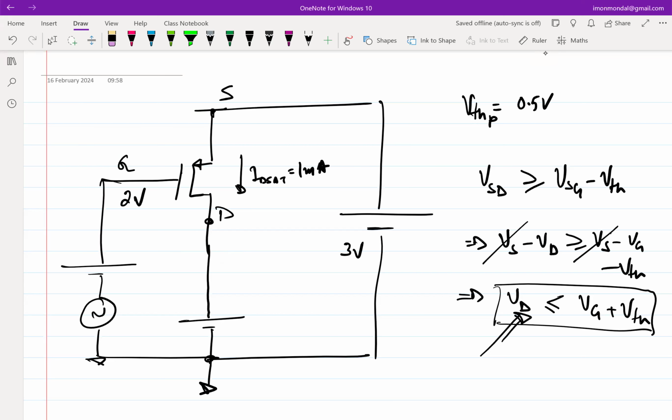However, this is not sufficient because ultimately we need to ensure that the incremental current flows into the load resistor. So we had to put the load resistor. Then we found out a few places where we can put it and a few places where you cannot, based on some practical problems. And then we saw that this is probably the best place to put the load resistor. And let's assume the load resistance value, I don't remember how much, but let's say it's 2 kilo ohm.